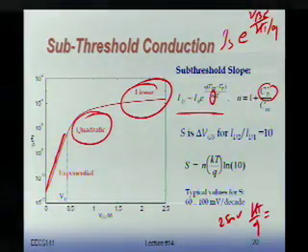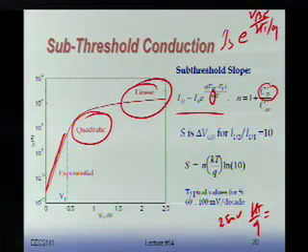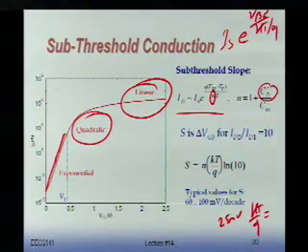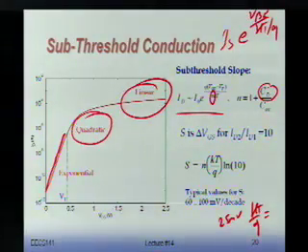Right? So N is going to make this a lousy bipolar transistor. It's not really a good bipolar transistor, but it's a lousy one. So you have to have that extra factor N, typically around 2-ish. Somewhere between 1 and 2 approximately. It's rare that it's going to be above 2.